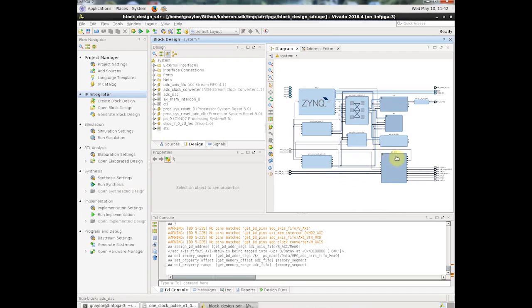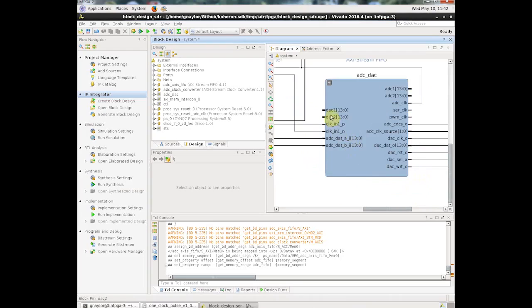The other thing we need is the signal from the ADCs themselves. If we have a look at this block here, this shows the data being streamed out from the ADCs at the ADC clock frequency, and we can stream data back in again to fire up the DAC outputs, and we're going to send the speaker output to one of these, again clocked at the same frequency, this clock here.